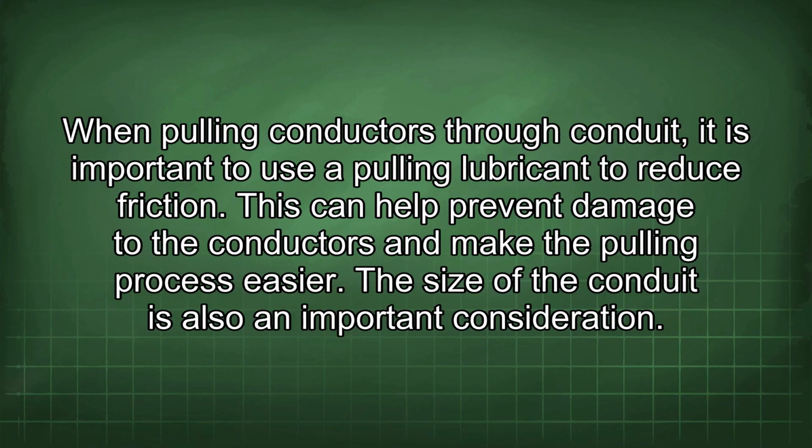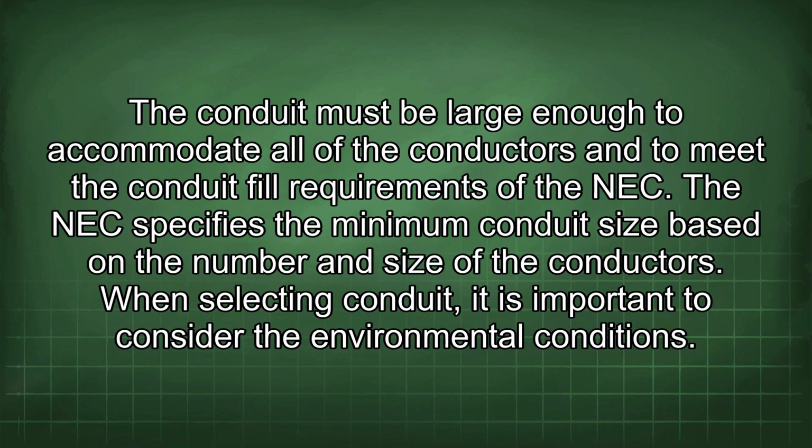When pulling conductors through conduit, it is important to use a pulling lubricant to reduce friction. This can help prevent damage to the conductors and make the pulling process easier. The size of the conduit is also an important consideration. The conduit must be large enough to accommodate all of the conductors and to meet the conduit fill requirements of the NEC. The NEC specifies the minimum conduit size based on the number and size of the conductors.